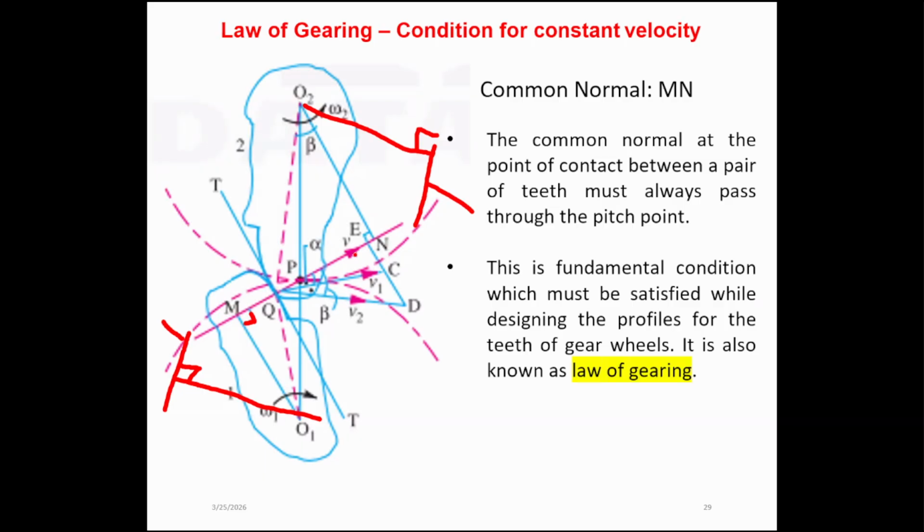So the law of gearing means the common normal at the point of contact between a pair of teeth must always pass through the pitch point, right?